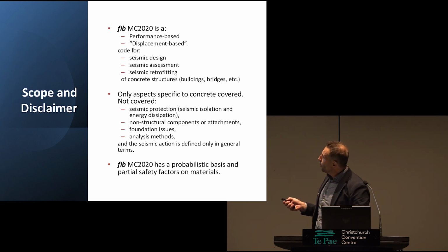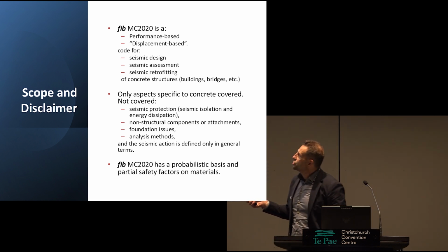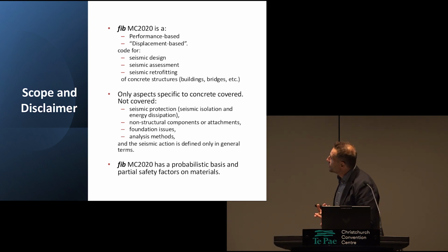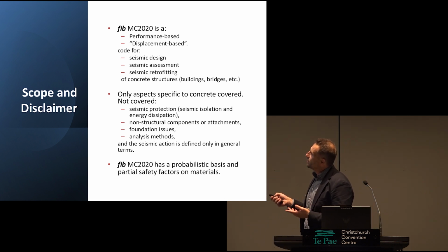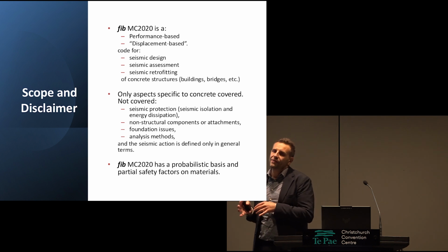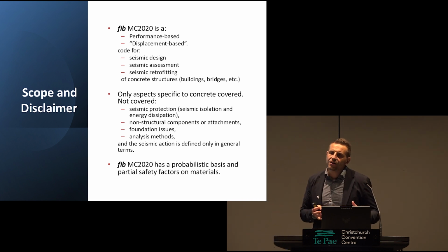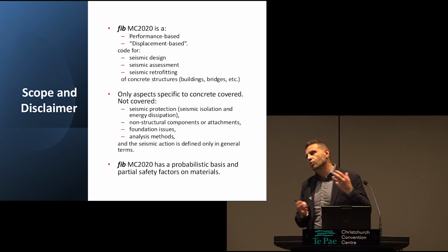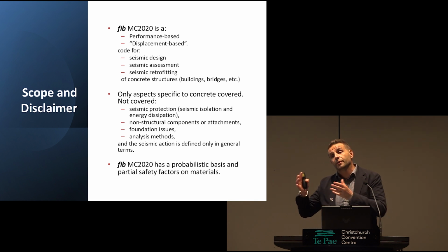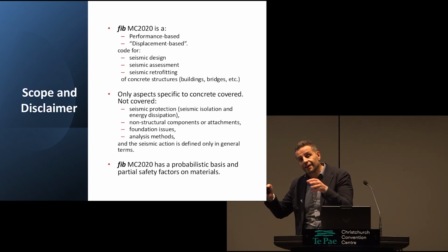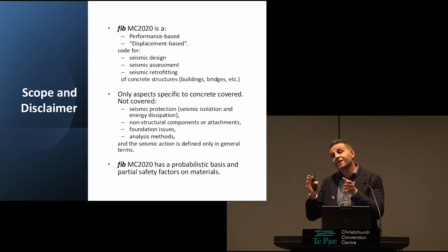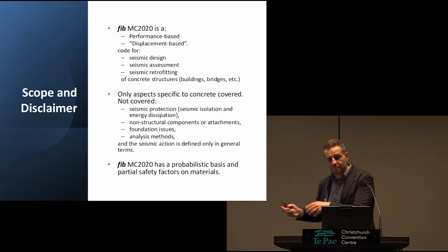And then also there are parts which are, let's say, material agnostic, like seismic isolation, non-structural components, and foundation issues, that are not covered. Although we may argue about that, right? Because, for example, for non-structural components, the way you connect the non-structural elements to the main lateral load system is actually very important. It can change the failure mechanism of the lateral load system.